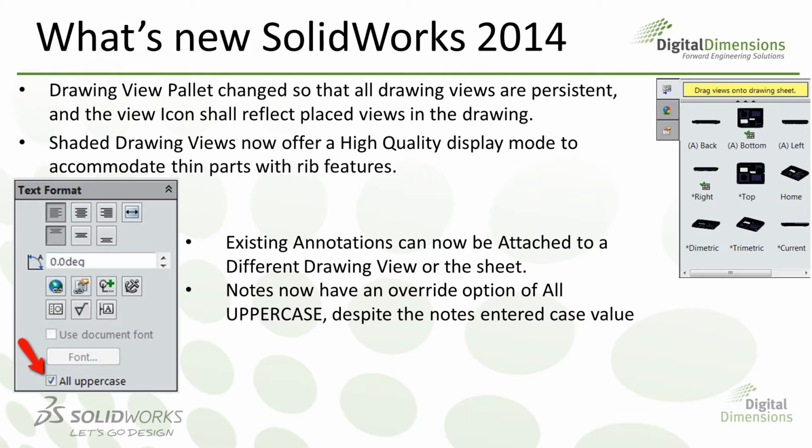Also, within a drawing, any notes that you have on your drawing can now be switched from one drawing view to another drawing view. So in other words, in the past, whatever view that you were closest to when you added a note, that's the view that it attached to. What's new for 2014 is the fact that we'll be able to reattach that note to a different view.